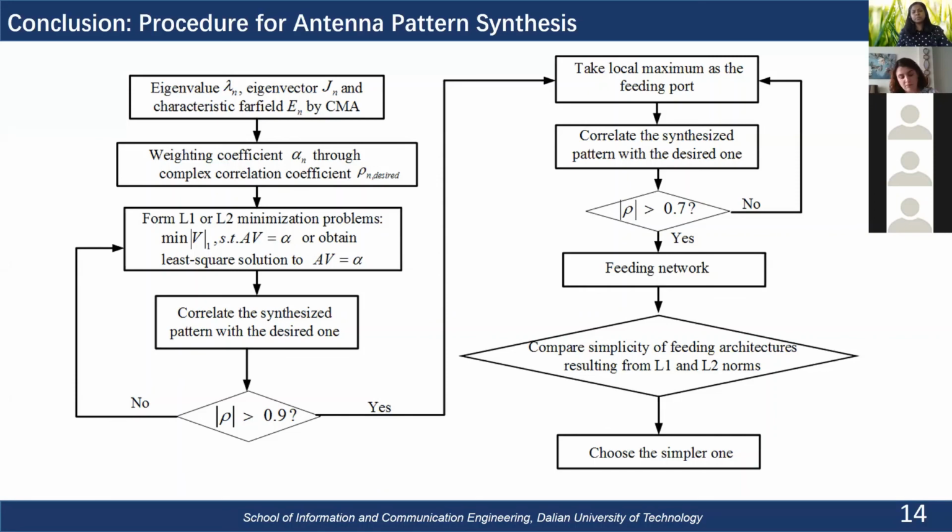But if you have different sizes in your RWG basis functions, then the Gramian matrix is not evenly distributed, and then you might get some troubles here. Maybe, I don't know whether you're interested, but if you want to check that, you could mesh something with different sizes of RWG and see whether this has some effect here. You mean that we mesh it in different regions, we use different meshes, something like that? Yeah. Okay, it's a good suggestion, and we will try to see that. Thank you.